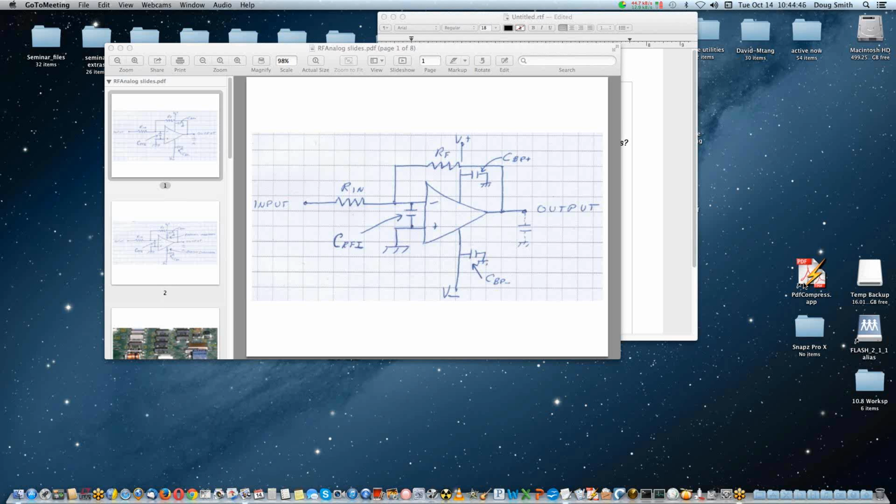Now that obviously only works if it's a 360 shield around the device and if the ground connection there on the board is clean. That is, not only is there a good series of connections around that shield, but is the ground itself low noise and is it low impedance to ground. If those things are all true, then the shielding can be effective.